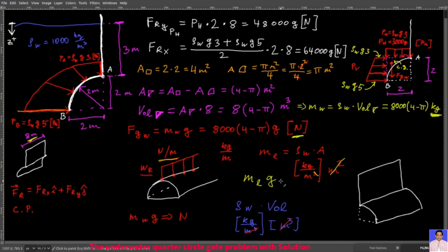And so the point that I'm trying to make is that now, instead of finding something like this, we will actually find 2-point forces that will act on one specific point, the center of pressure. And while we have to find the center of pressure on this arc, if we consider the length of the wall, which is 8 meters, then because the shape of the arc does not change in this direction, nor does the depth of the arc change along this direction, in other words, nothing changes as you go along the length of the wall, we know that the center of pressure is located in the middle of this 8-meter distance.